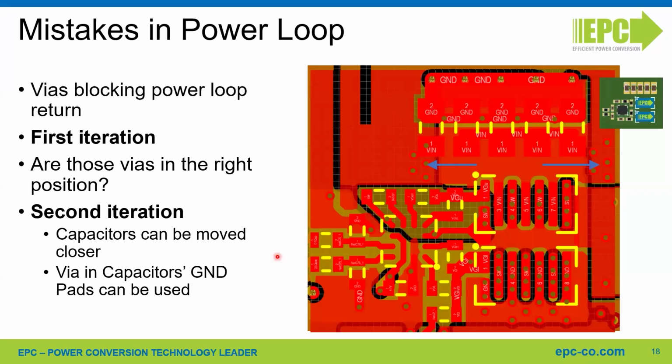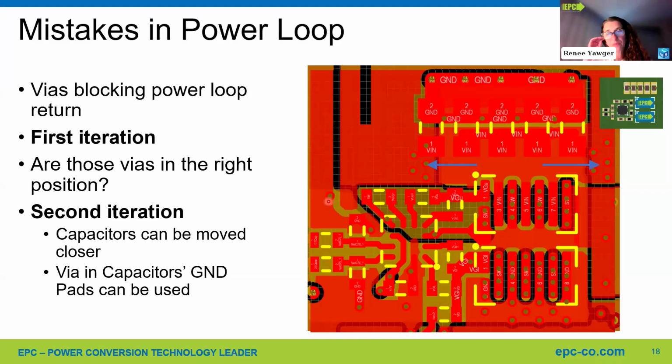Okay. Should the signal ground containing the sensors and PWM signals be the same ground as the power ground, totally isolated from each other, or a small net tie 0 ohm resistor connecting between them? In this case, the interface is the gate driver, if we limit to the driving circuit. So the ideal connection point between the power ground and the control ground is in the close vicinity of the tracks that are bringing the PWM signals to the gate driver.